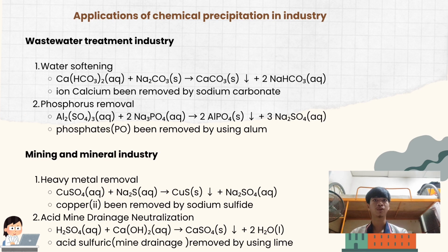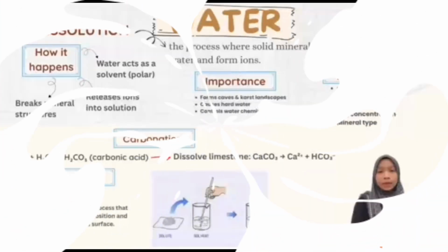Lastly, in mining operations for heavy metals, there is a high possibility of generating very strongly acidic or alkaline wastewater. To prevent this, miners usually use calcium hydroxide to neutralize the wastewater before discharge from their operation.